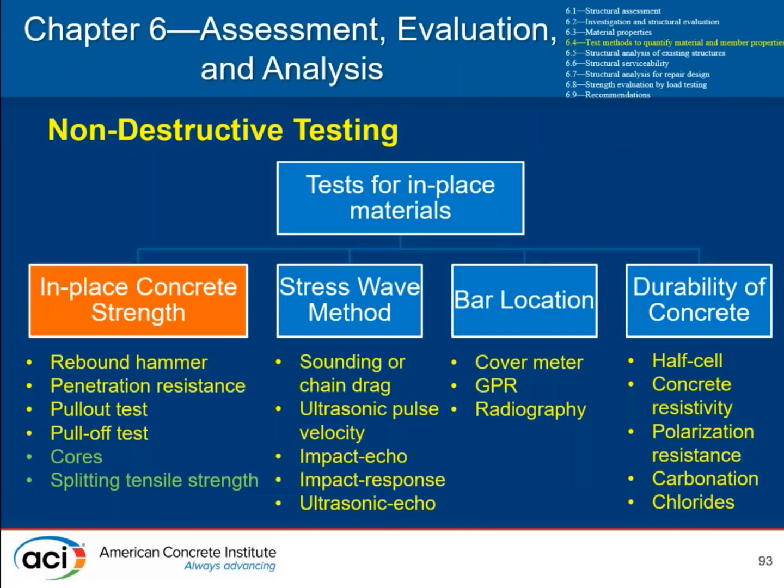This slide lists the various non-destructive methods for in-place materials. The rebound hammer, penetration resistance, and pull-off tests require calibration using compressive core strength tests.